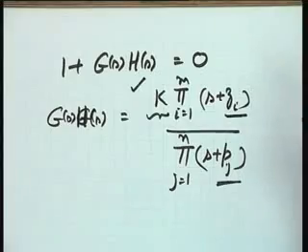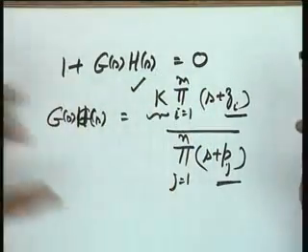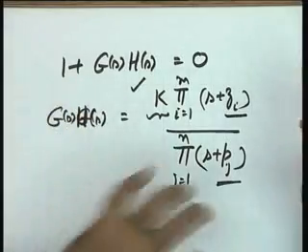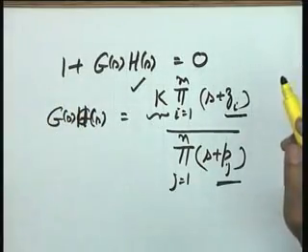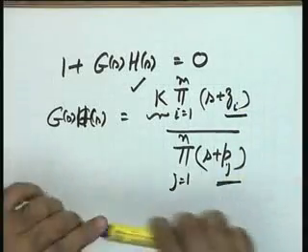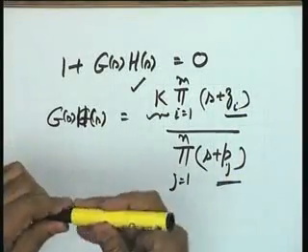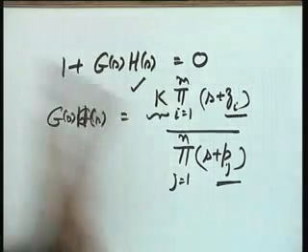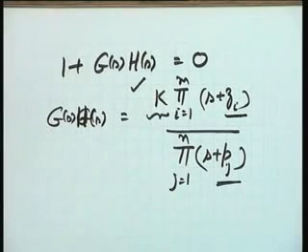Okay, any form it may be. This form is more convenient as far as the root locus sketch is concerned, and therefore I make a sketch with respect to this particular form. Okay, zi's and pj's will be positive values if these poles and zeros lie in the left half plane, and normally they lie in the left half plane, though right half plane possibility is not ruled out.